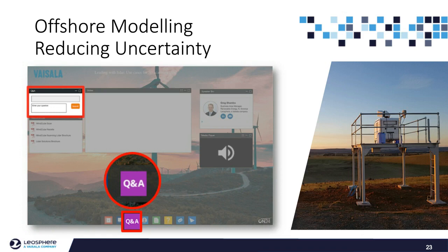Yes, the scanning WindCube is designed to resist tough environments. Its components are integrated in an ultra-resistant one-piece fiberglass casing protected by gel coat finishing. It is waterproof with an IP65 rating and resistant to salty environments, so it can be installed whether on a fixed platform or near the coast.